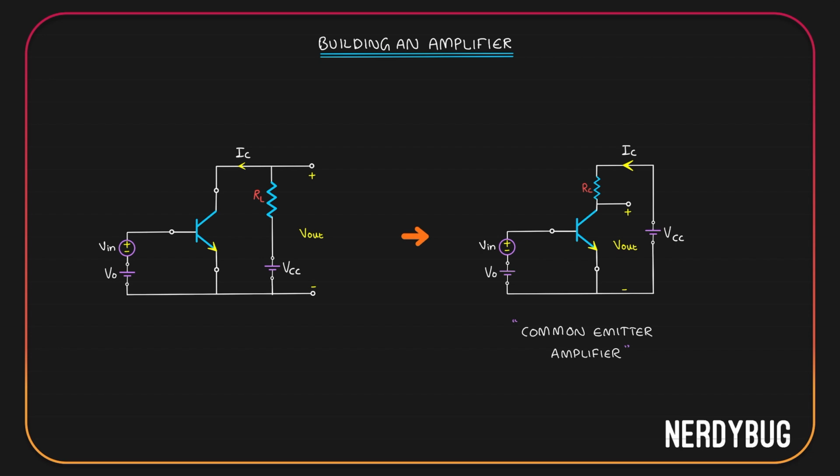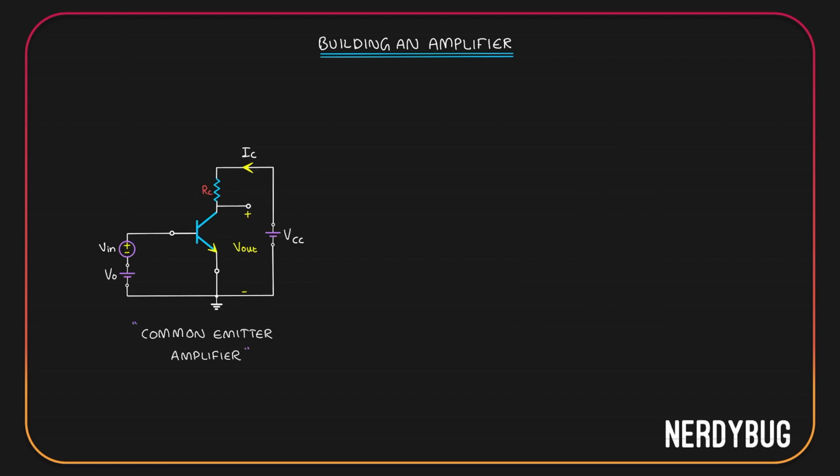Now, something else we can do here is this. We can consider the potential of the lowermost point to be 0 and define the potential of every other point with respect to that. This technique was used to solve some problem in the last video. Basically, what we are doing is taking the lowermost point as the ground. Using this idea, we can represent the same circuit in a much simpler way like this.